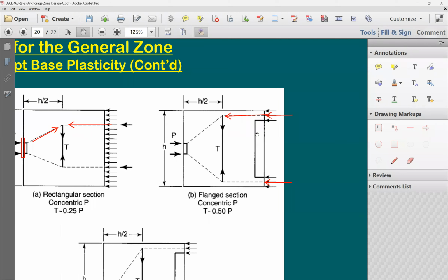So in beams like this, when you have an I shape, I'm expecting here to have more tensile force. Because look at the slope of this line compared to the slope of this line. What happened here when I have an I shape, I push the force, the compression force, to be more into the flange, because I cut lots of concrete from the middle here. I just created a thin web.